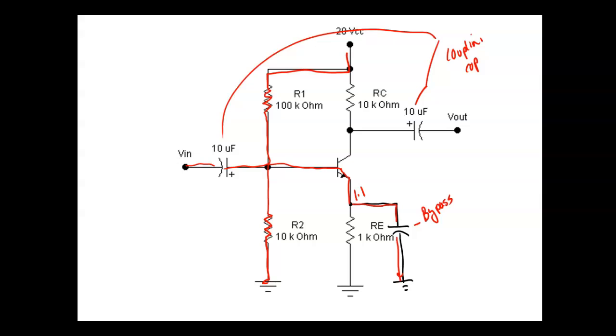So what is my gain? Well, you're going to say, I don't know. So what we have to do is deal with this. We know that when we come over here and forward bias the junction, it actually comes over here and does this. Everybody okay? So we deal with what we call the dynamic resistance of a PN junction. This is when we put AC on.